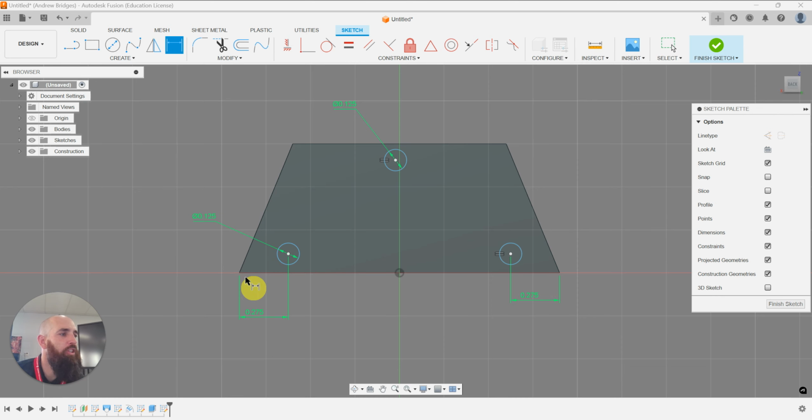And when we do the vertical dimension, we're once again going to use the point up to the center point, and that's going to be a vertical dimension of 0.125. And all we have to do now, as you might have guessed, is, let's say horizontal vertical, the center point and the center point. And there we have it.